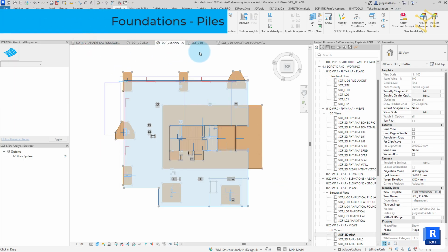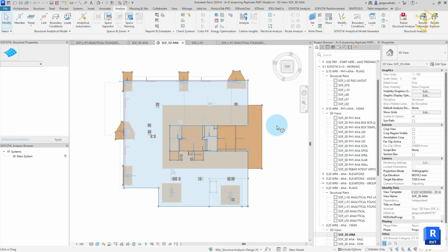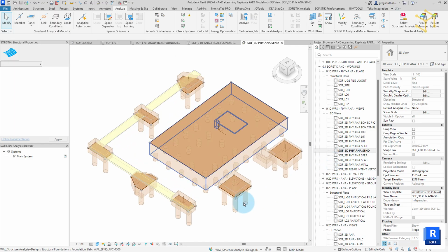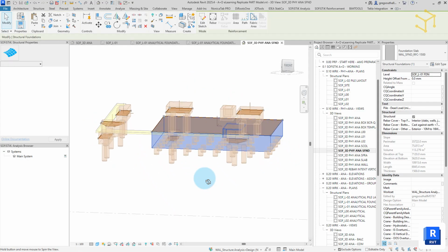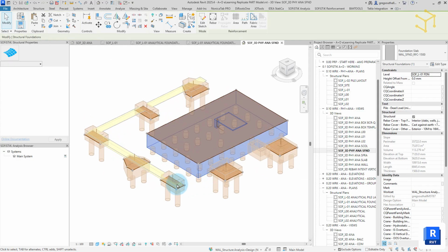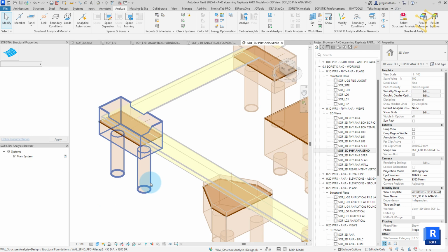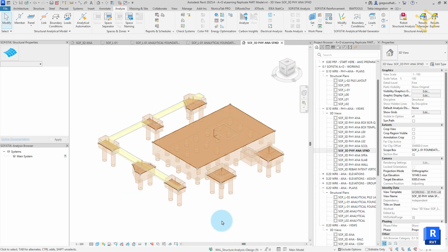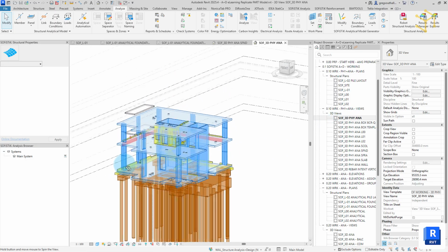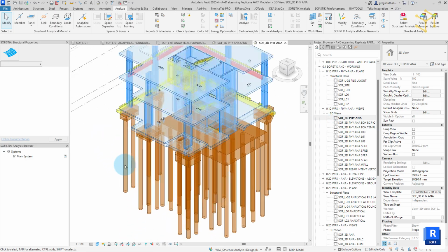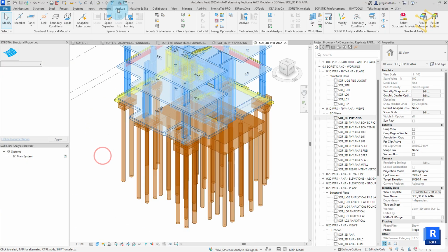To continue the replication exercise, we'll now address the piles. We'll use the copied physical pile elements to our benefit to generate the analytical counterpart. Autodesk doesn't allow the creation and placement of individual analytical nodes, so we instead use generated elements to provide the end nodes that we can then subsequently apply analytical boundary support to. After, we'll automatically apply the pile reference to our subsequent boundary support conditions. Let us begin.